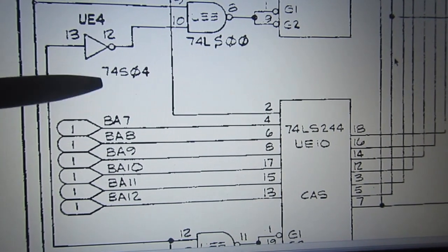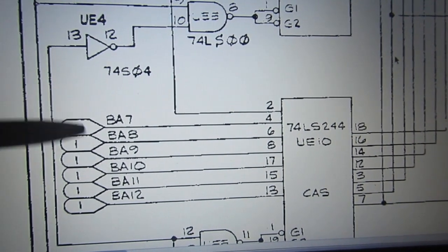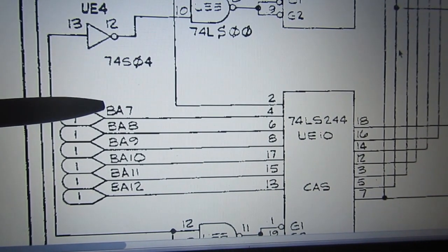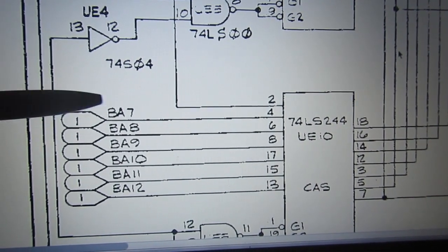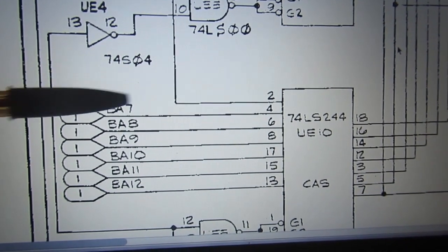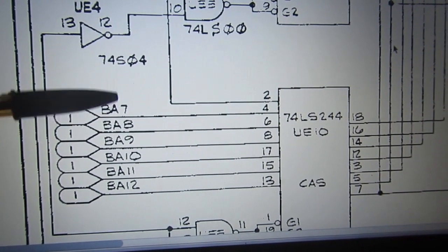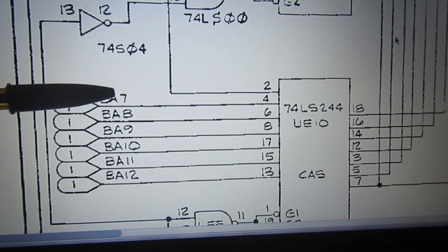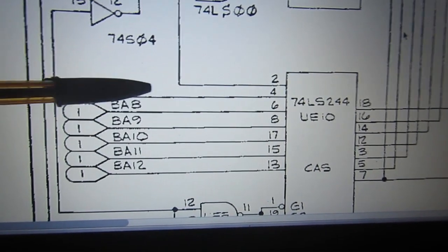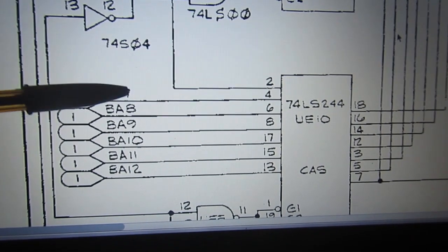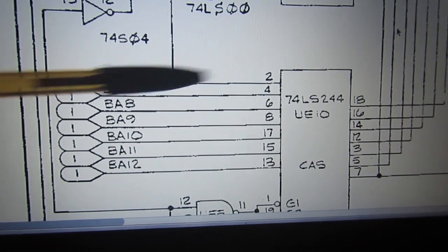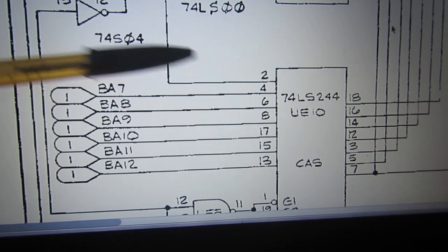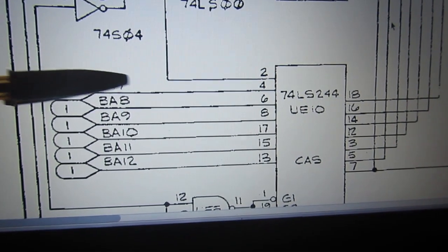And the other reason that could explain also why the test reported the address 7 as bad, probably because the fault was triggered by address 7 going to 1, and the first part of the test was probably not testing address 7 as 1 until it got to the end of page 0, or start of the stack test.